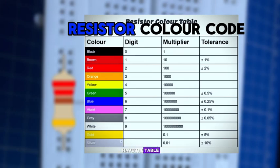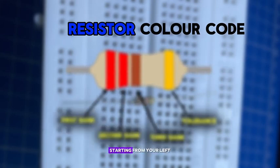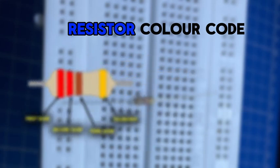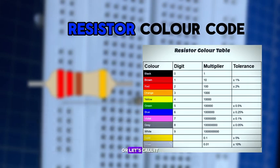So now that you have the table, let's take a quick look at how to read the resistor color code. To read them, hold the resistor such that the tolerance band is on your right. The tolerance band is usually gold or silver in color and is placed a little further away from the other bands. Starting from your left, note down all the colors of the bands and write them down in sequence. Now, use the table given to see which digits they represent. The band just next to the tolerance band is the multiplier band. So if the color of this band is red, representing 2, the value given is 10 raised to the power of 2, or let's call it 0, 0.